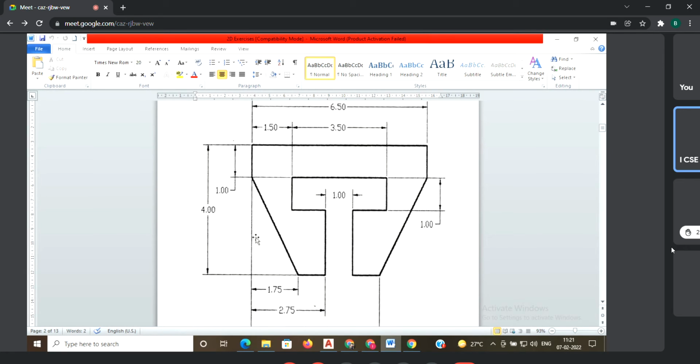And already you know this chamfer or fillet command. Okay. Chamfer or fillet commands, you have no. Okay. First I will draw a horizontal line and a vertical line. Why? Because the horizontal length I know, 65 mm. The vertical, meaning height, I know, 40 mm.